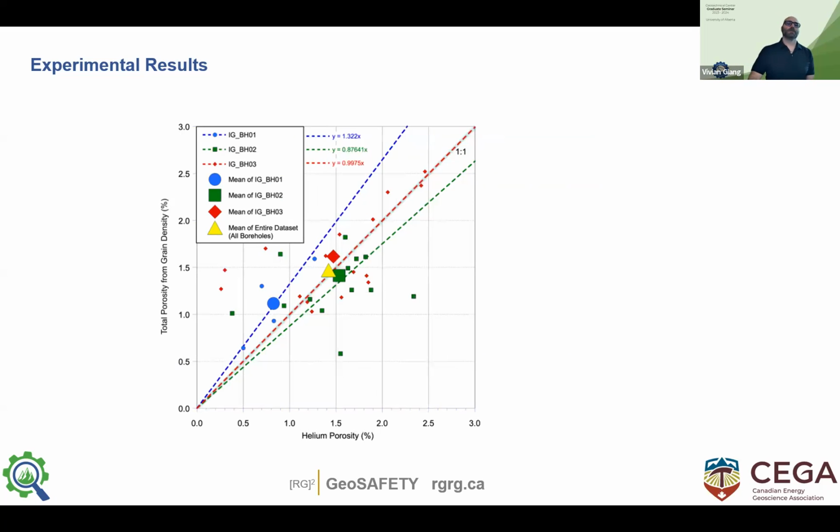The porosity for this particular work is ranging around 0.5 up to 2.5%. We measured that by completely drying the specimen for helium porosity, and then also through grain density crushing, and then through water loss porosity. Each of those measurements uses slightly different approaches, looking at slightly different permeability or porosity measurement techniques, and accessing more or less pore connectivity.